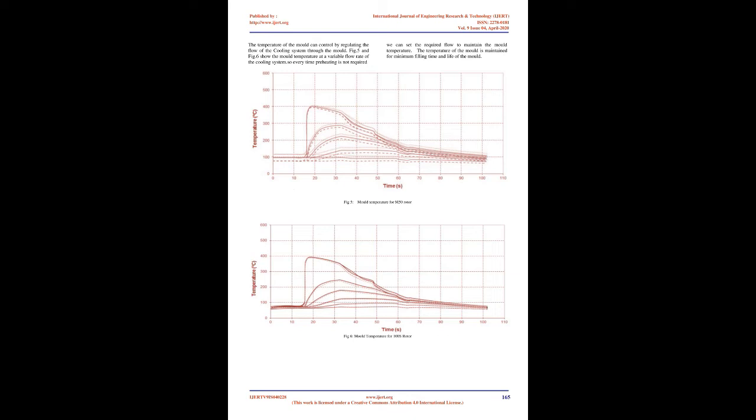The temperature of the mold. The casting quality is significantly affected by the temperature regime of the mold. When the mold is cold, joints are formed in the casting and the surface quality of the casting is insufficient. When the mold is very hot, the alloys are bonded to the mold and the amount of bubbles and pores grows. The temperature of the mold will be maintained constantly at approximately 1/3 of the temperature of the cast metal. This is achieved by thermoregulation of the mold.